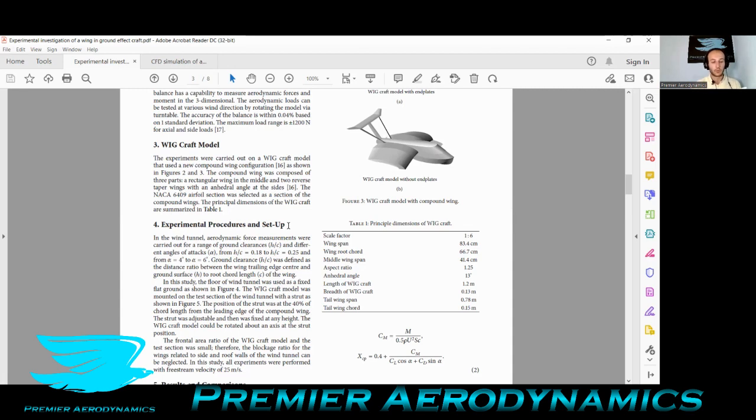In this study, the floor of the wind tunnel was used as a fixed flat ground. So let's talk about that a little bit more. What does that mean? It means that it's a typical wind tunnel that you'll see almost everywhere, where the surface on the ground is just a flat sheet or whatever it is. So what happens there? When the flow goes over any surface, as we know, in real life, a boundary layer forms. Now in CFD, you can always assume a slip condition, but in real life, it's always a no-slip condition. So that means that a boundary layer always forms.